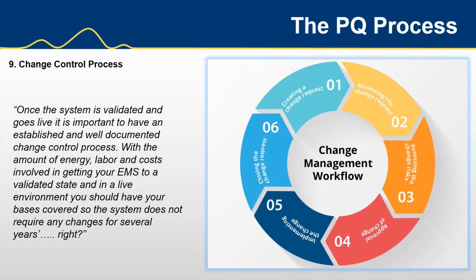If changes are required following your quality change control process, then updated SOPs and training around change control are mission critical. The last thing you want is an auditor looking at your EMS audit trail and noticing alarm limits were changed 6 months ago, and there was no change control documentation to support the change.